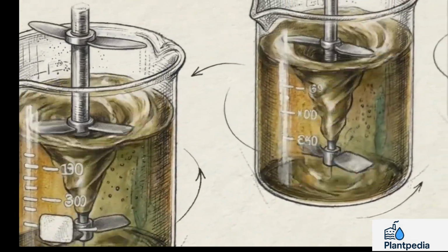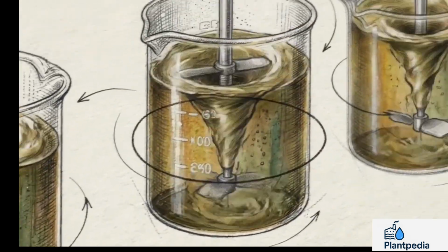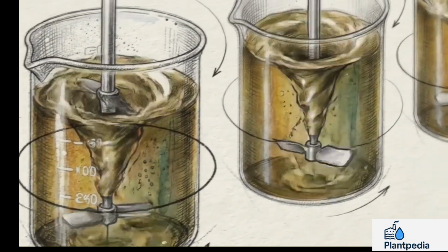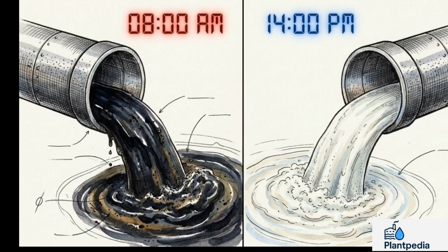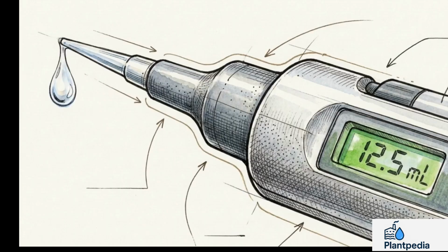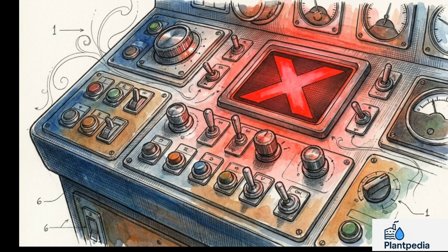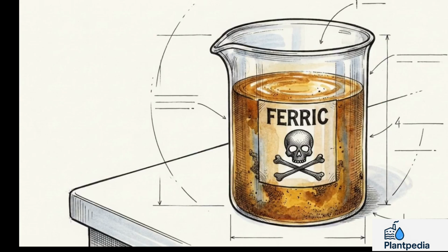The jar test utilizes a benchtop mechanical stirrer to simulate the plant's exact real-world flow conditions on a microscale. It allows engineers to physically observe flocculation speeds and sludge settling times. Because daily wastewater characteristics fluctuate based on production schedules, the jar test is required to pinpoint the exact dosage of your chosen chemical for that specific day. Applying an incorrect dosage, even if you have selected the mathematically correct chemical, will cause the process to fail, leading to outcomes like the yellow water associated with a ferric overdose.